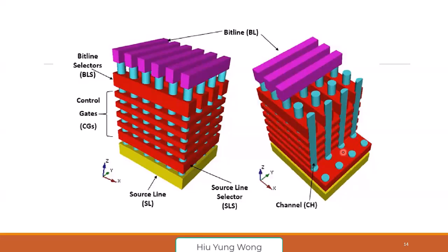In MEMS, we have something called Bosch etch. If you heard about that, Bosch etch. But that is more for relatively larger features, and they don't care about the so-called scallop. Bosch etch is something you can use to get very high aspect ratio, but it's not very clean. But here we're talking about nanometers. Maybe Bosch etch can also do that, maybe 10 nanometers or even smaller.